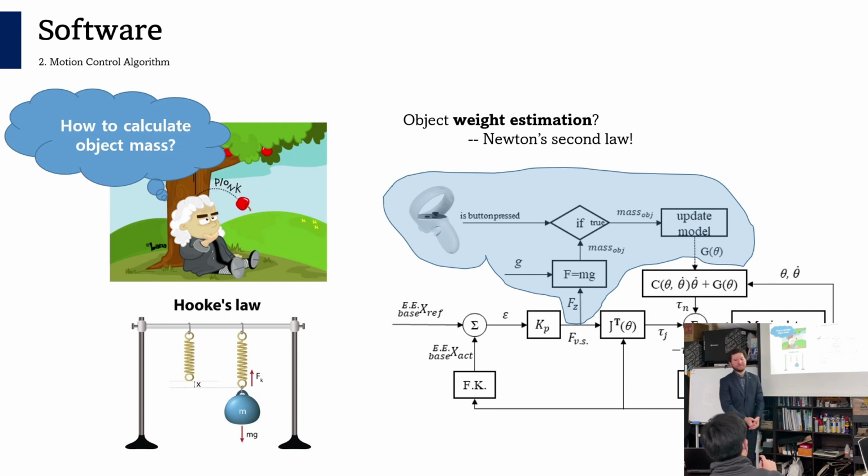What I'm suggesting is that first you need to update a mass for gravity compensation for the static position, but in order to make satisfactory dynamic conditions, you may need to update the moment of inertia of the entire system and use a model-based system. For example, LQR, or if you want robustness, you can use a sliding mode control. That might be your future research. That's my question.